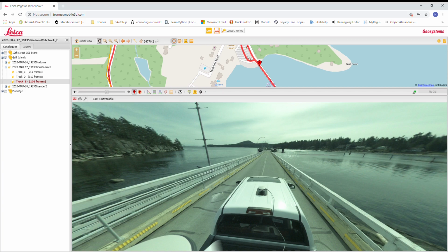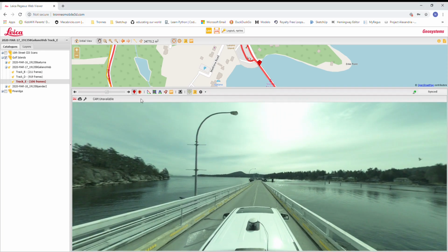The next group of tools you can use after enabling the Use Point Cloud to snap on picture option, which is that green button right here. And now we can measure a 3D distance. Blue is vertical, green is horizontal, and red is slope. You can disregard the orange number again. And these measurements can be copied to the clipboard if you desire.